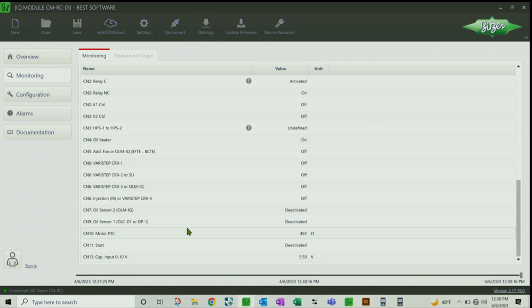It's telling you that the unloaders are all off because the compressor's off. There is a slight delay because the unloader energizes and the screen has to update. But in a minute when I reset this, you'll see those go from on to off as they energize and de-energize. So you can use this for troubleshooting to make sure the relay is closing. Even though the screen says it's closing, if it's not closing because it's fried internally, then you can check that. It should be closed, and if I'm measuring it's not closed, something's wrong.